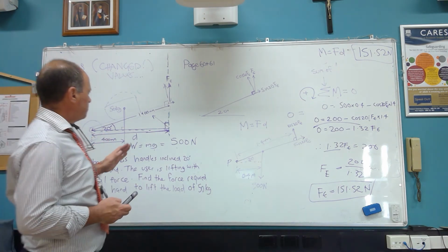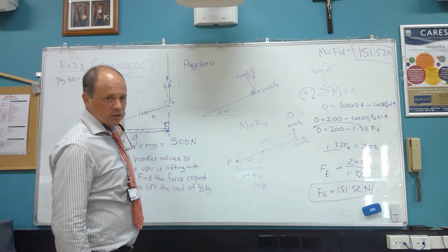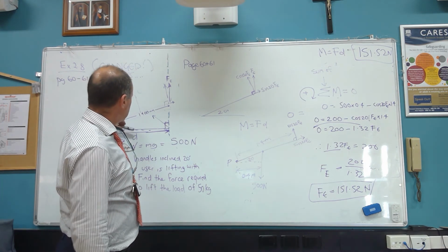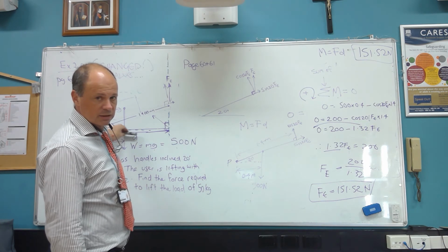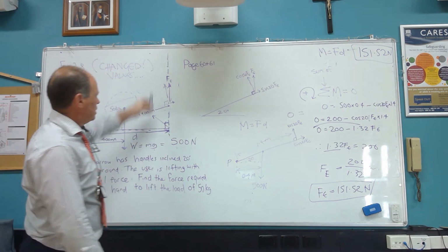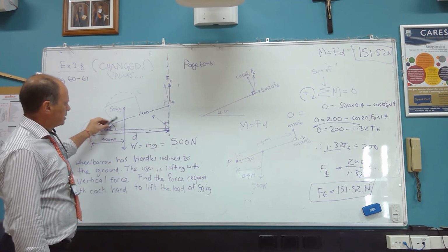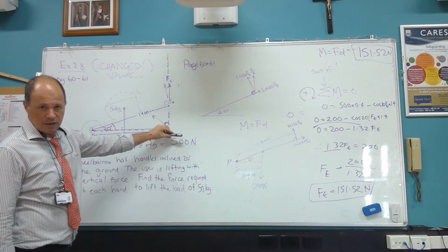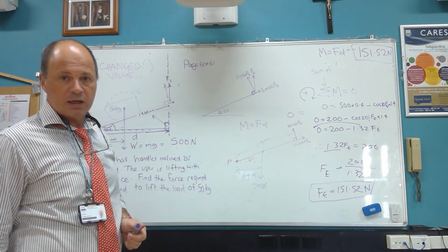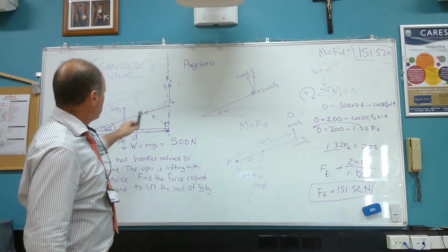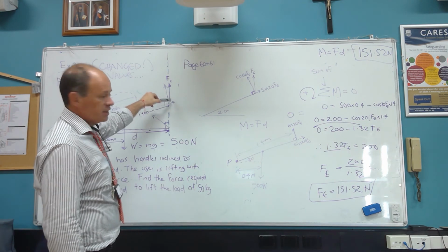And like I said, finding perpendicular distances, you just extend the line of transmission and then move the arm until you find where it intersects at 90 degrees to that force. Okay, so extend the force, transmissibility of forces, move arm until you hit 90 degrees with that line that's made. That's your perpendicular distance from the pivot. Okay, two methods. One, we use the actual length of the arm and component of vectors.